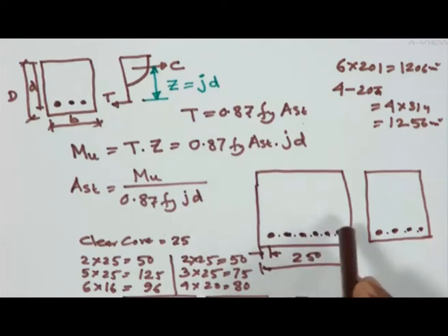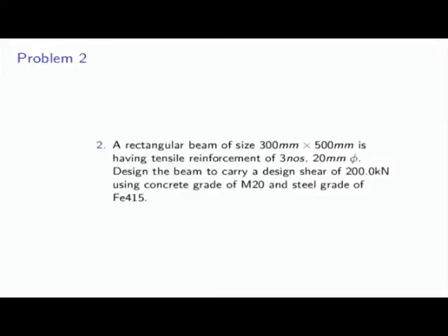That is another part. Second one, that 250 millimeter is the thickness of the wall. Now let us say you give some value, say 275 millimeter. Obviously a certain portion will go out of your wall, so that also does not look good. So these are the different conditions you can find out. Here it is better to go with the increase in the diameter of the bar.